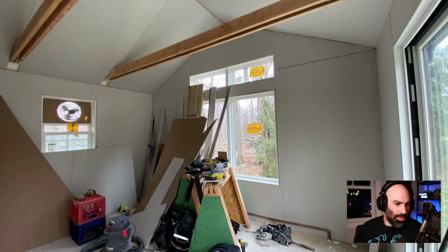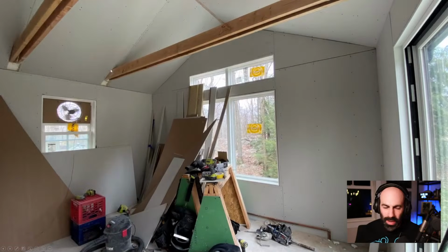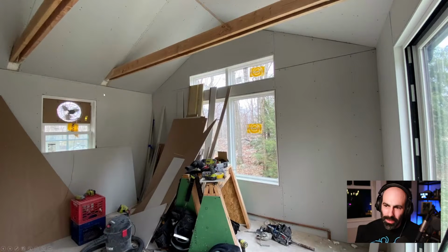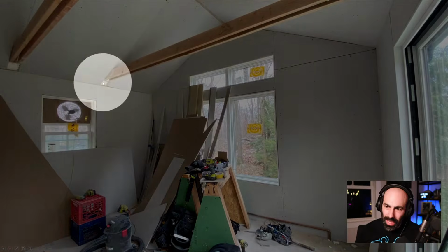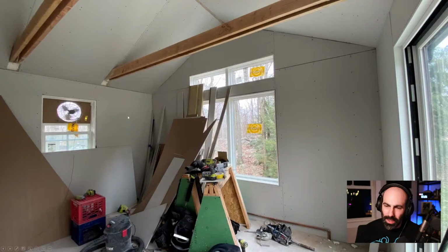And then upstairs, here's some drywall here. This is a little piece here that I'll talk about in a minute, which is again one of those things that you don't think about as an architect as much as when you're going to build it, and it usually comes up after the fact. It's, what do you want to do for drywall around this, right? How do I clean up this drywall? If you put a piece of drywall just across here, it's just going to crack. If you try and tape and mud this, it's going to move, etc.